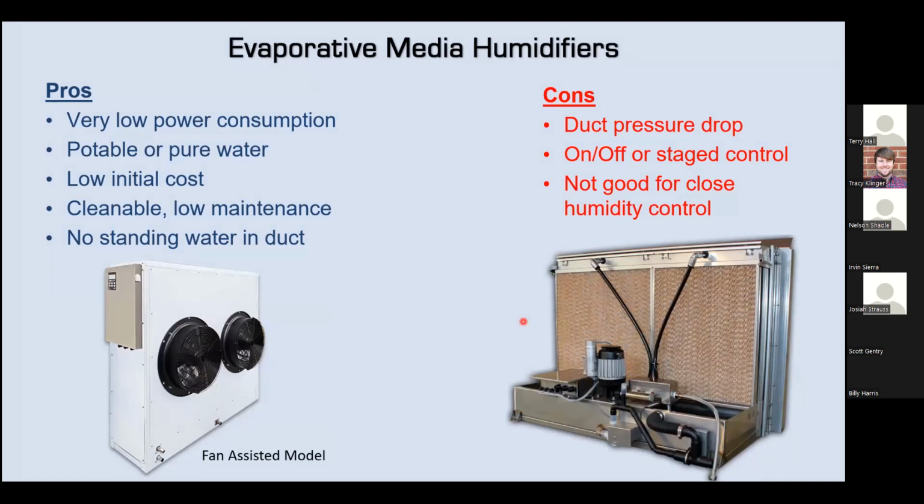Evaporative media. This is something we've seen a lot of data centers focus in on because they're generating heat with all of the equipment, and this can be a solution, and it can be either ducted or a fan-based solution. So you can have a fan model that's basically like a swamp cooler in the space. I've seen a lot of these go in places like the Southwest, where you can have free cooling in the space in either a ducted or a